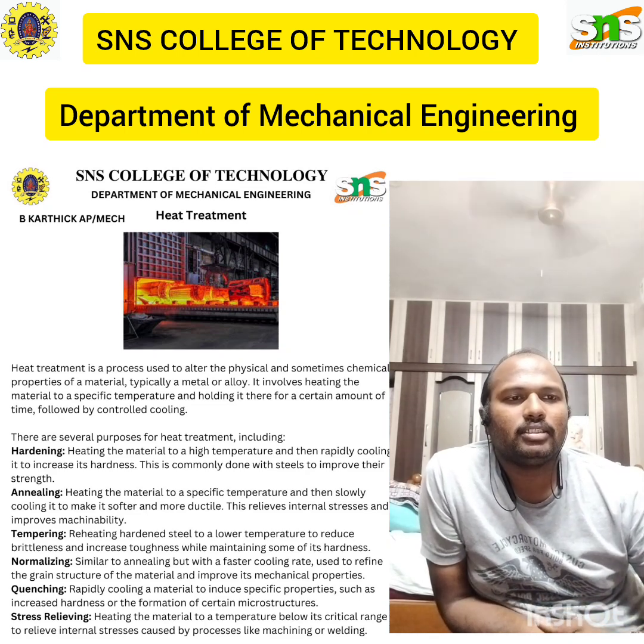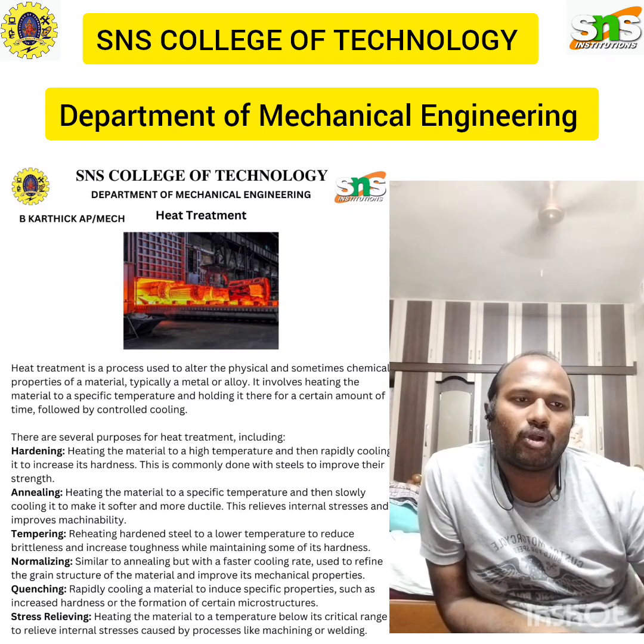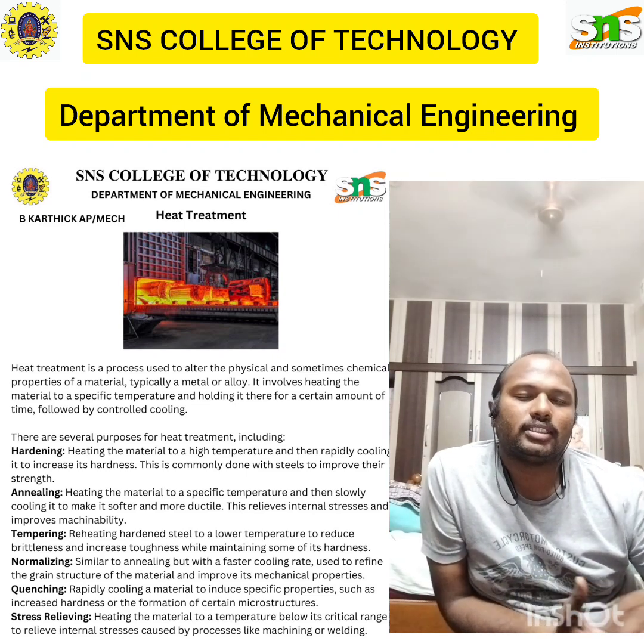Coming back to normalizing, at a specific temperature and cooling it in air, to refine the grain structure and to improve the mechanical properties. The last one is quenching: rapidly cooling the material in a quenching medium such as oil or water to achieve specific properties like hardness and strength.